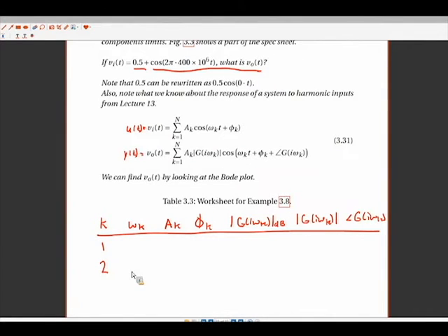All right, so the very first term is 0.5. What is the phase of just a DC voltage of 0.5? Or sorry, what's the frequency of a DC voltage of 0.5? I heard 0 from somewhere in this region. 0? Okay, so why is it 0? Yeah, so it's not oscillating. If we were looking at the plot for 0.5, time is just being held at 0.5.